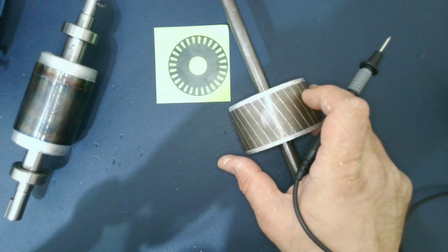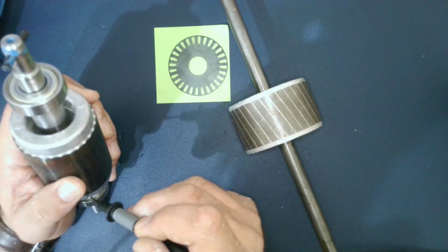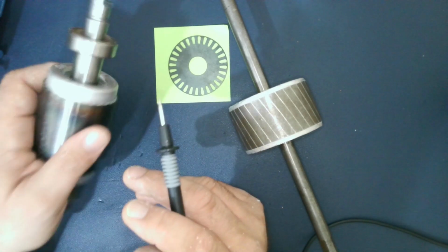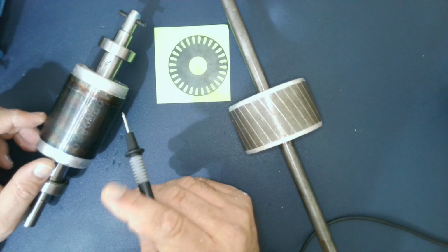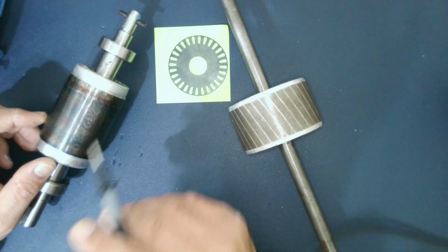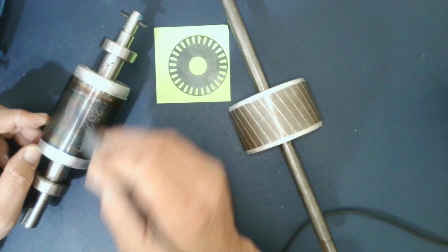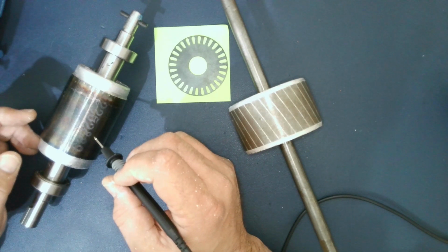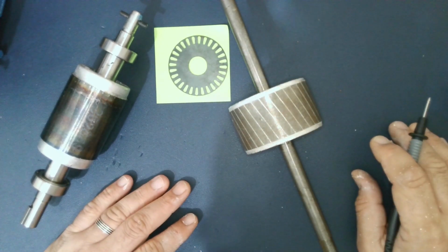Two questions here. We notice for this motor that the bars are straight, not skewed. So should we skew that one? Not all motors have skewed bars, because this motor is 0.55 kilowatt. When we need high performance, we need to skew these rotor bars. So in some motors you can find them not skewed, just to make the construction or manufacturing easy, because skewing the rotor bars complicates the manufacturing process.